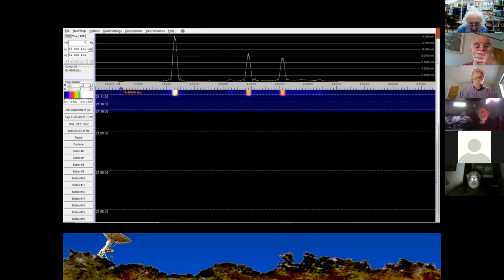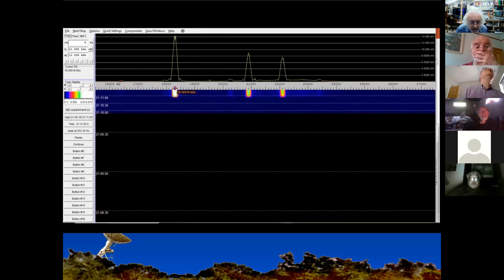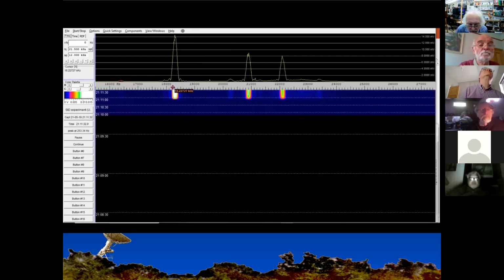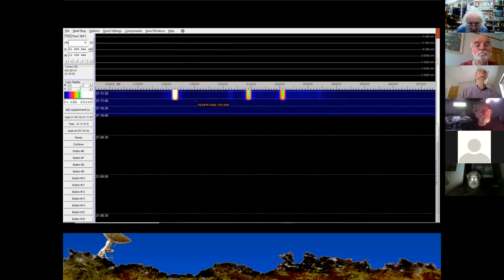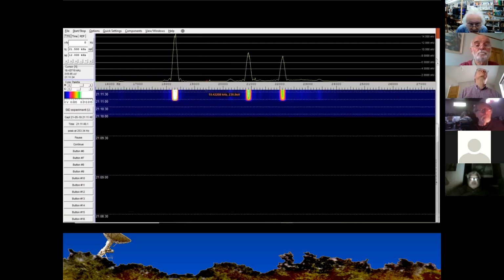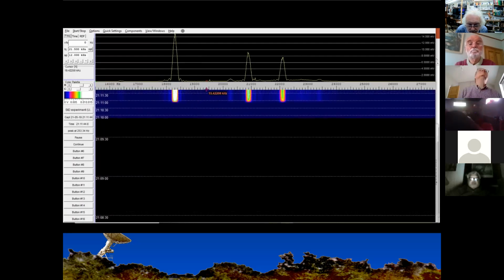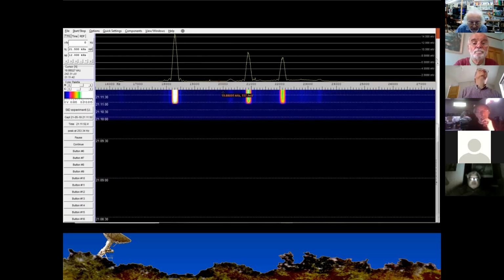So we can come along the list here. This very weak one down here will be in Norway. This one here, 18.3 kilohertz, I think is a French station. Desperately looking for my list. 18.3, Rosnay. 18.3 kilohertz is Rosnay in France. We're missing one of the usual stations, Anthorn in Cumbria, which is at 19.6. That tends to go off at night at the moment.